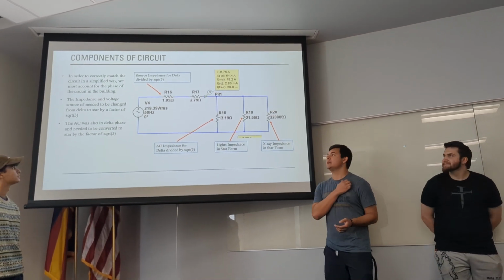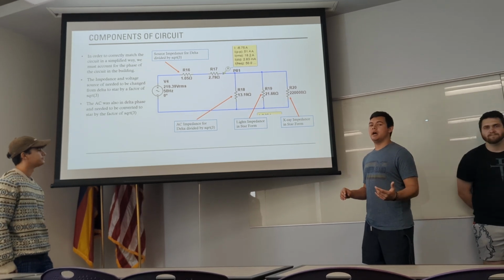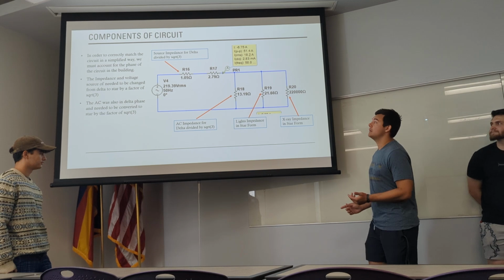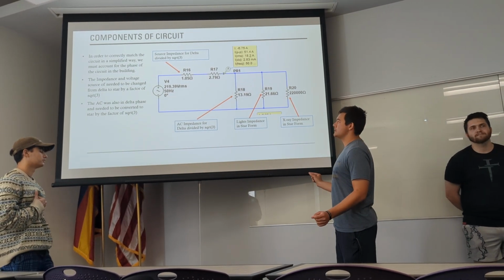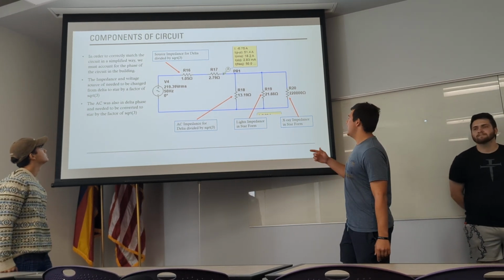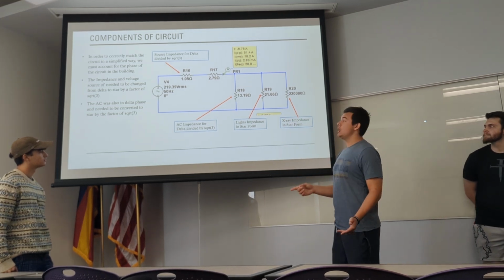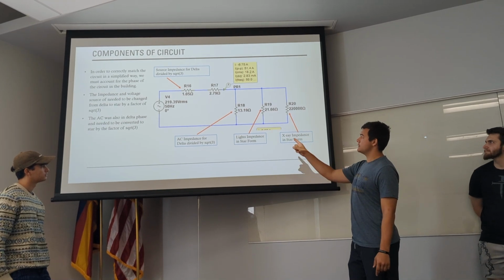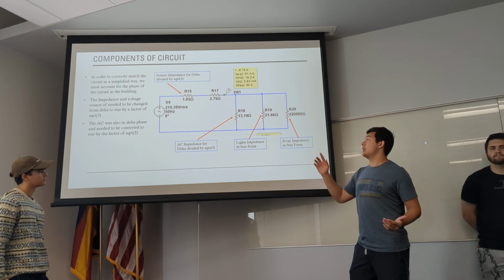Awesome. So breaking down the circuit here in Multisim, we were able to take our values from there and analyze the circuit. Like we were saying before, we had to convert some portions of it from delta form to star form. More specifically, the impedance from the source, there was a small resistor and inductor that we had to divide by square root of 3 in order to convert it, as well as the AC, which we also had to divide by square root of 3. Then taking our values calculated for impedance, we have the simplified full circuit here that was able to give us our voltage and our current up at the top there.